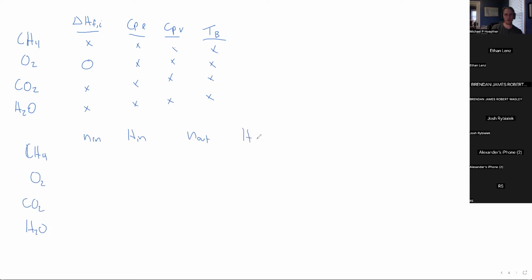And then I can basically build my table where I have CH4, O2, CO2, H2O, and enthalpy in and enthalpy out, right? And then for methane, I would build my formula: delta H formation plus the integration from 25 to T, C sub P vapor dT, right? And then I would reference these cells. Then if I drag this equation down, I would be populating all of my calculations and I only have to type in one formula. Does that kind of make sense how that works, everyone? Yeah, that's crystal clear. Yeah, good. Thank you. So then, that's why it's sort of nice.